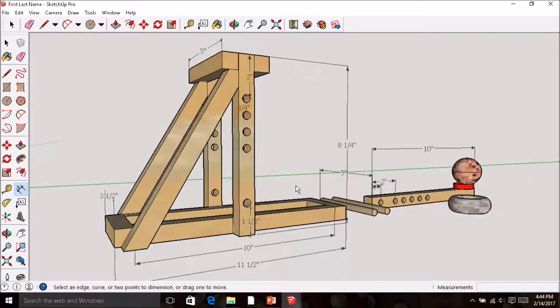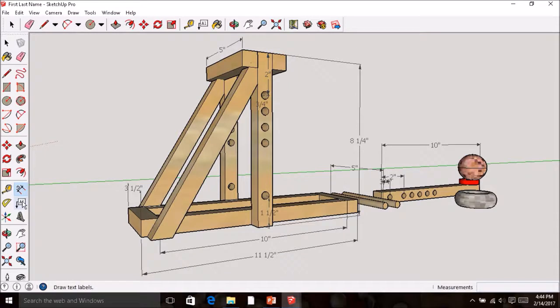Once you have it where you can see everything and you've zoomed extent, the last thing you need to do before you print is you're going to select text, or the leader command right here. And you're going to click somewhere off to the side, and up here you're going to type your first and last name, period, whatever number it would be. And you're going to simply click off to the side and you'll see it's listed up there.